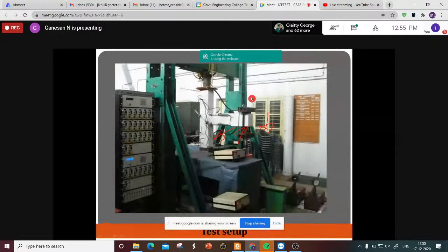Now you can see this is the specimen. You have the LVDT at the top and bottom to measure the steel strain, that is the strain at this point epsilon C, and the strain at the bottom epsilon S, depending on the loading. Then for the rotation, we measure the shear strains using the diagonal LVDT, and this is the arrangement.